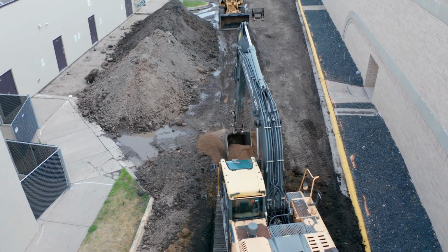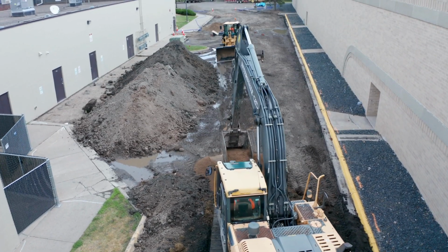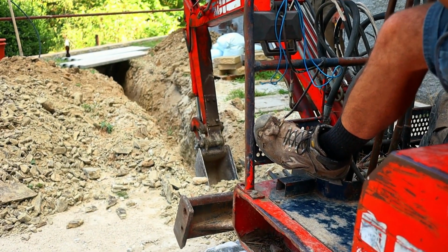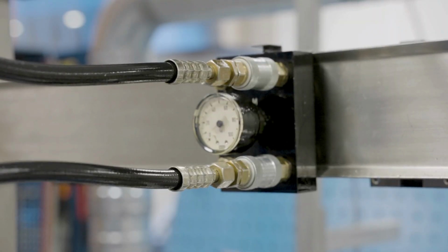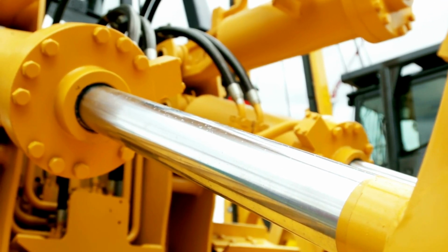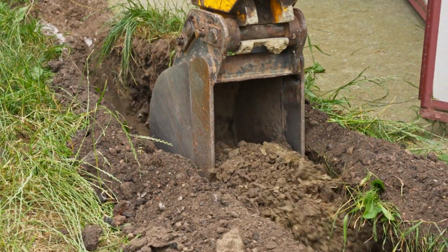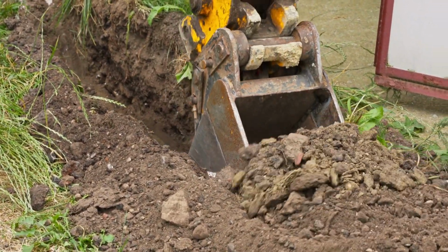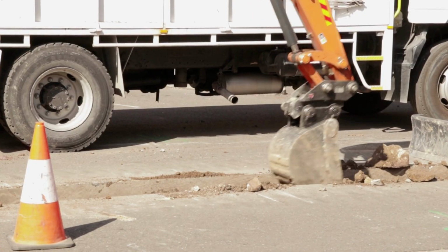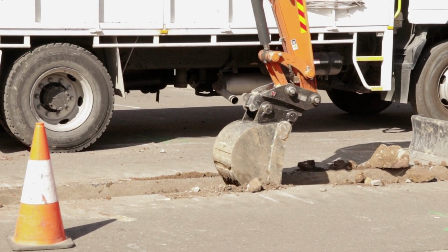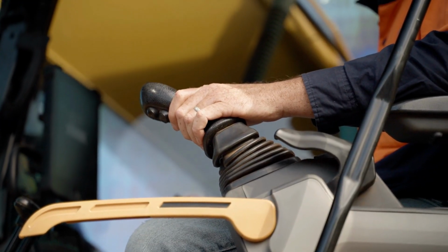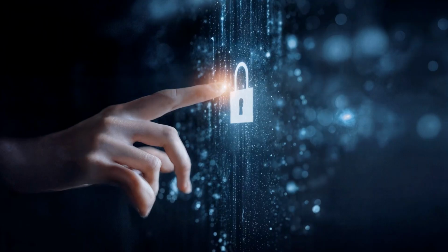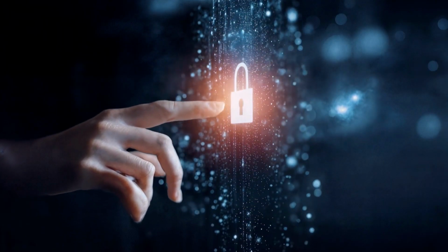This position information is then used to control the hydraulics more intelligently. Instead of moving cylinders blindly based only on joystick input, the excavator adjusts hydraulic oil flow based on position error. As the bucket approaches the target, the error becomes smaller, and cylinder speed is automatically reduced. If the bucket reaches the target or a safety limit, further movement in that direction is restricted. The operator may continue moving the joystick, but the machine will not allow incorrect motion.